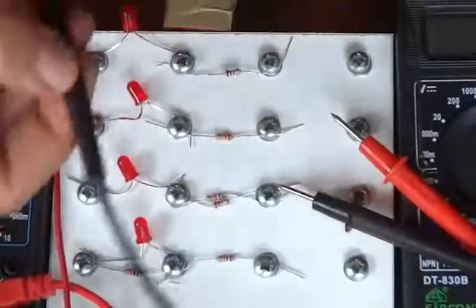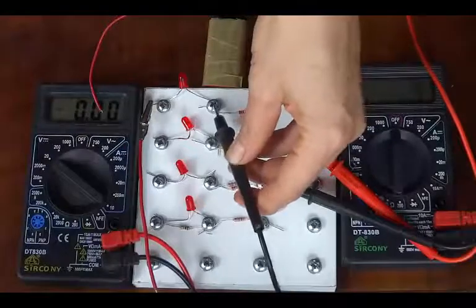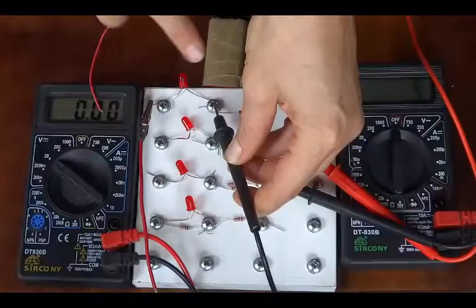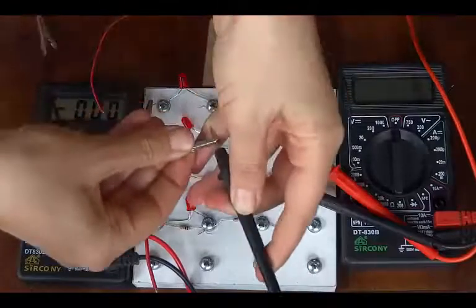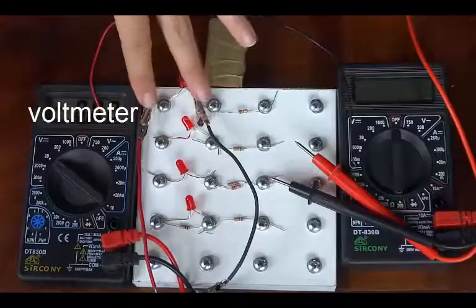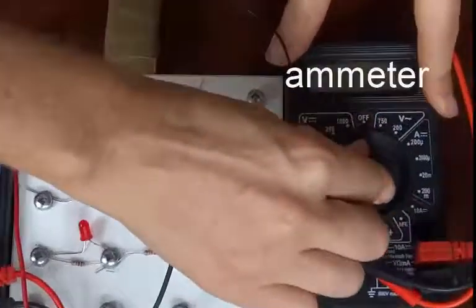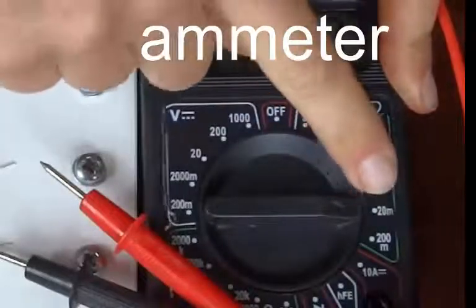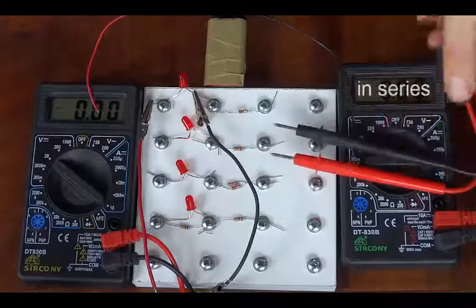And then this is the negative probe of the voltmeter. So if the circuit was connected, then this would be measuring the voltage across the LED. And let's use a crocodile clip there as well to hold that in place. So we have the voltmeter in parallel across that LED. Now we need the ammeter here, which we set at 20 milliamperes maximum. An ammeter must always be connected in series.